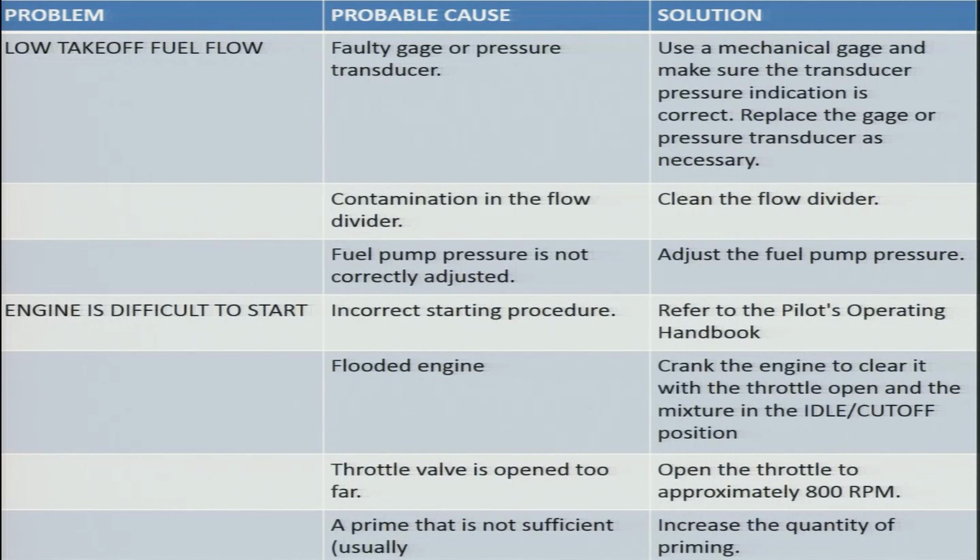Throttle valve is opened too far. So, the throttle valve is too much opened. In that case, your engine is difficult to start. Another reason is that the prime is not sufficient. So, your priming is not sufficient. So, these are several reasons you have seen why the engine is difficult to start.